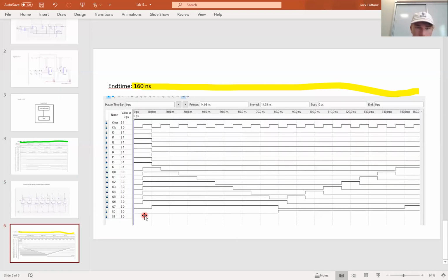So the implementation of this is we started here by entering an 8-bit of all ones. So 8 ones in a row. Then we have our 8-bit output here. To begin, the outputs are all at 1. Then here it is shifted 1 to the left, shifted another to the left, another, until they're all down to here. It's shifted to the left 7 times, so there's only 1 of them on. And then it's shifted to the right, so the 1s come back, shift to the right, and then they're all on.